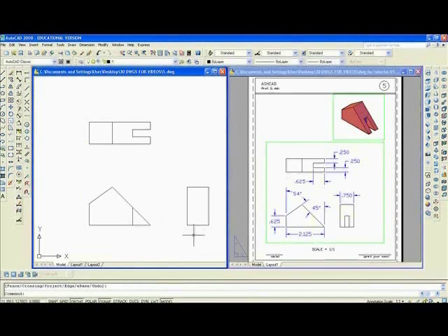Now we have to complete the right side view. And so we're going to enter, 0.25 enter. Here to here, and move that over that way. Then draw a line from this point here. Then fillet it with radius 0, that area.